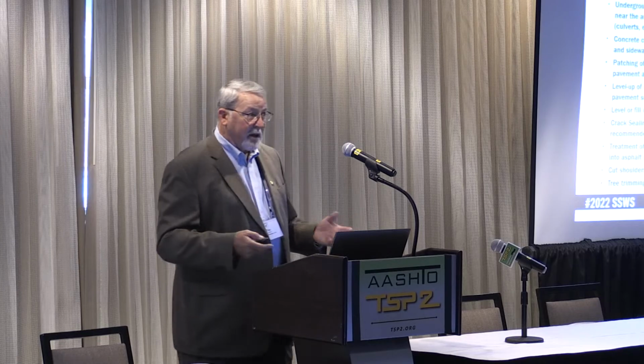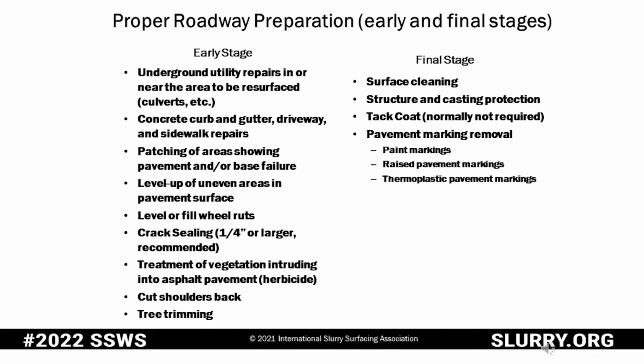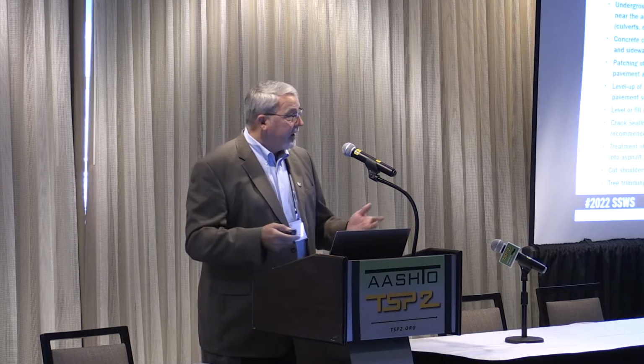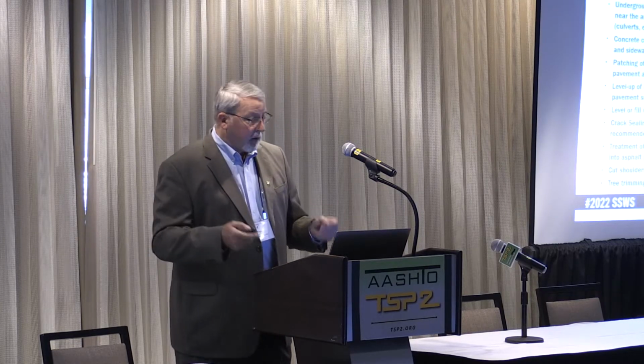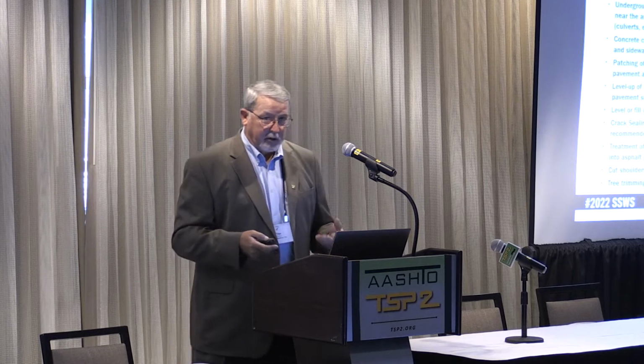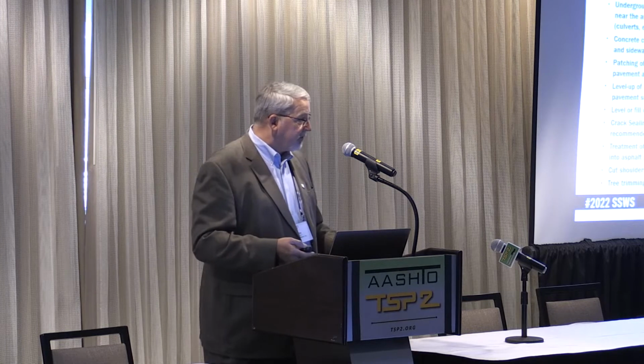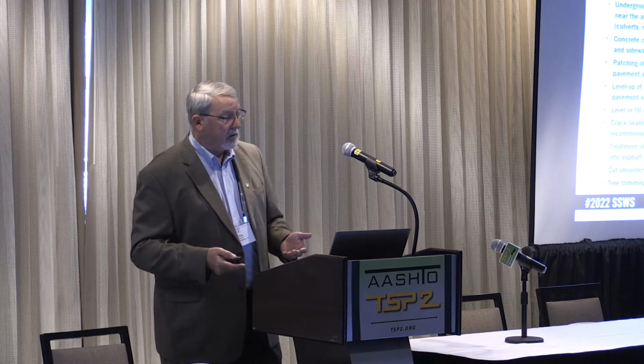Tack coat, I don't know if you guys use tack coat up here. We do not. I haven't tack coated a microsurfacing project in 30 years. We do not have delamination issues in the South, so it's not a big deal. The only time you need tack coat is if you're looking at an extremely oxidized pavement or it's concrete or brick, and then you may consider doing a tack coat under those circumstances.